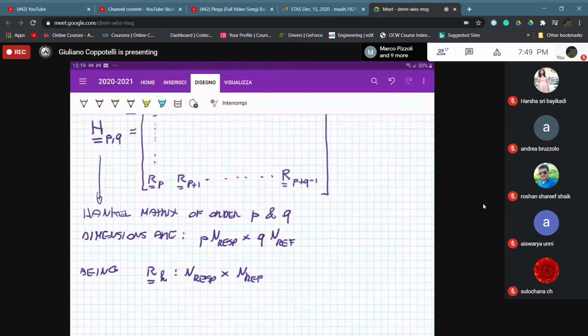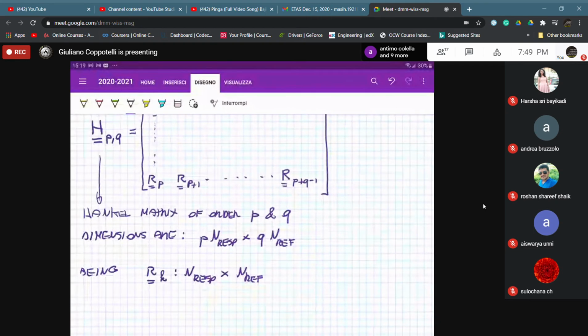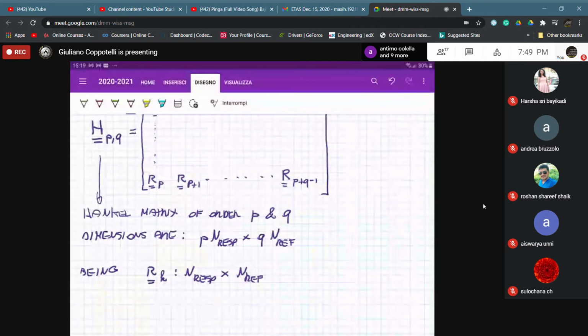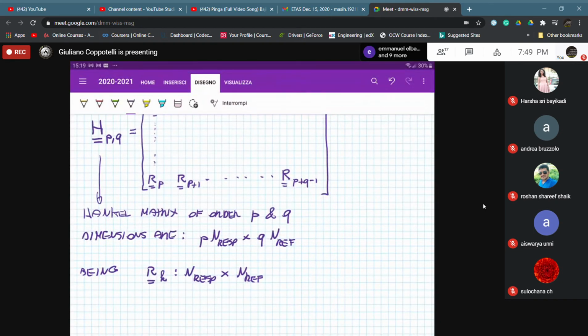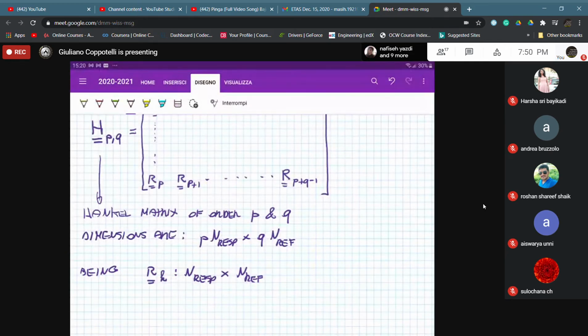Maybe you can add two or more at the midsection of the wing, and so on. Or if you are considering the whole 3D dynamic behavior of the wing, maybe you can consider additional reference channels, because you are evaluating your correlation function considering those channels.